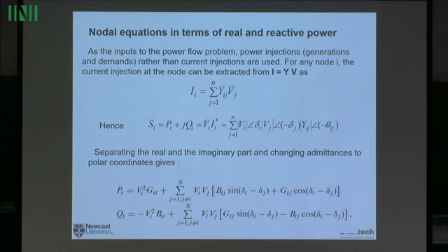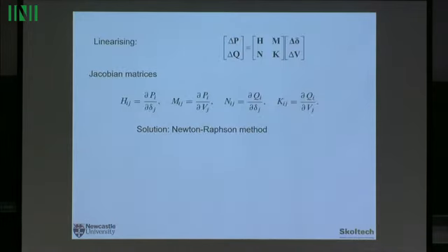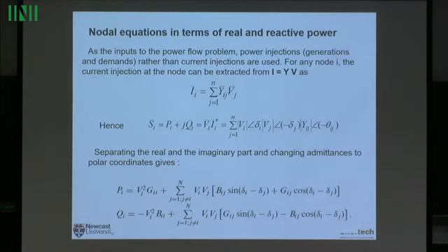I was talking about that with respect to just one line. Because it's nonlinear, we can linearize it. Basically, take the... Can I ask one question? Sure. So when we go back, this is all based upon the model where a transmission line is always a resistance followed by a capacitance. Resistance, inductance, capacitance, pi. So you're right. This is the pi equivalent model. Now I'm trying to simplify it. This is the most accurate model, when you want to model everything. But now let's go into simplifications which are useful for some simplified analysis.